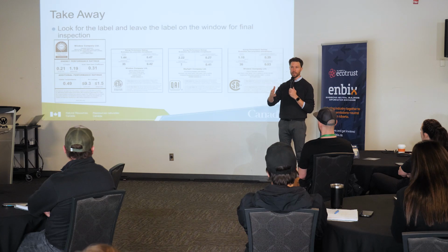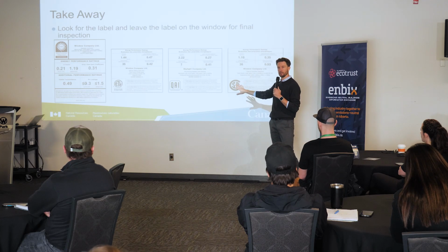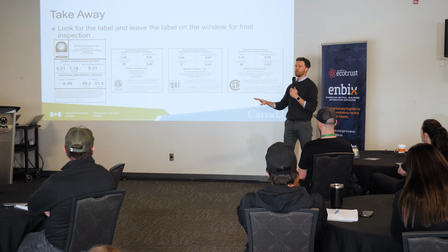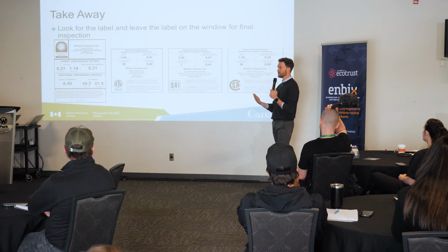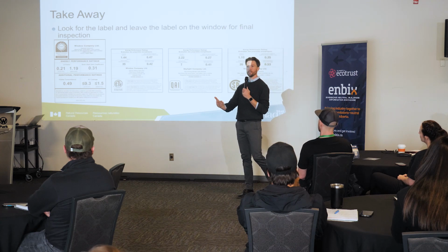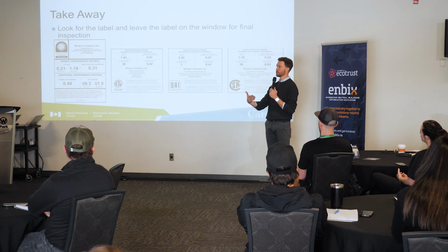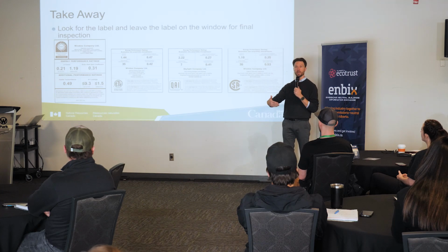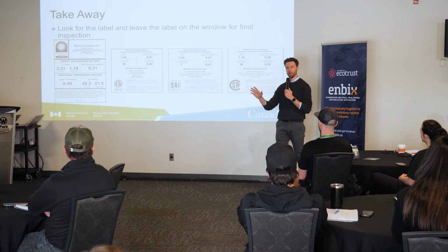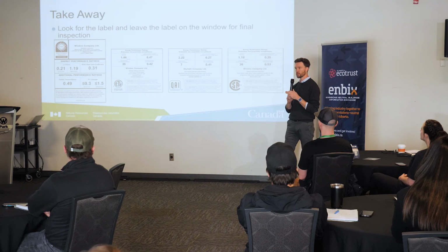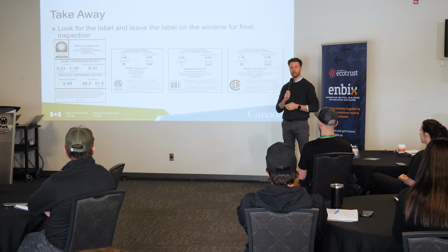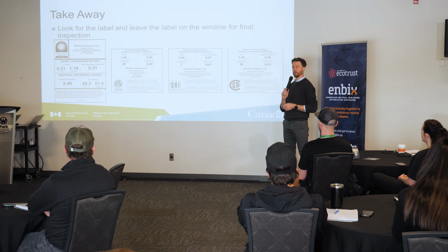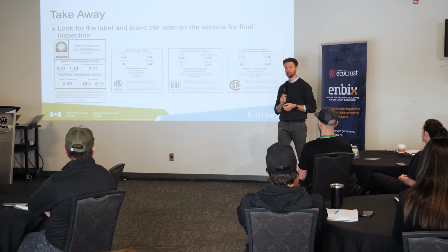To answer your question directly, it won't negatively impact these numbers in a significant way. But it will be uncommon, because where do we usually see tempered glass in these assemblies? We usually see it on the inside pane for protection against breakage from the interior. But the reason wildfire wants it on the exterior is because that's where the heat stress is coming from an exterior wildfire. Everything is sort of flipped. So it's another whole day to explore wildfire resiliency questions and hail and wind, which are all risks across Alberta. But as it comes to windows, it's another exploration point for us collectively to learn more about. It's a great question.